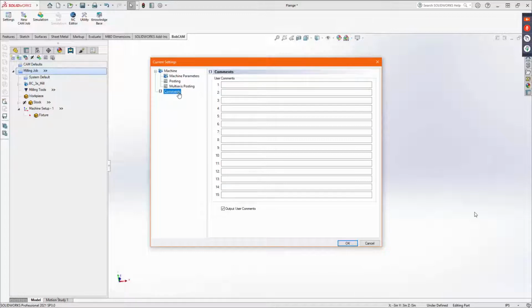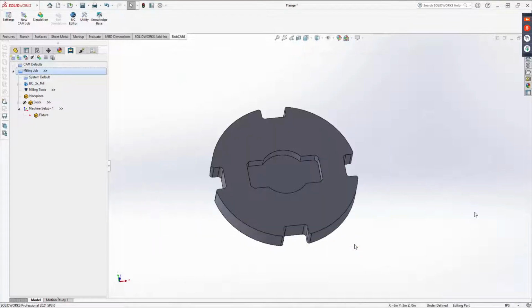So if it's information for work offsets, if it's just information for the operator, so they know, 6 months later, if they have to rerun the part, what they had to do to set up. Maybe little things like, hey, we had a 1/2 inch this time, but double check tools for next time. We may need to change them, things like that. The comments can be very handy.